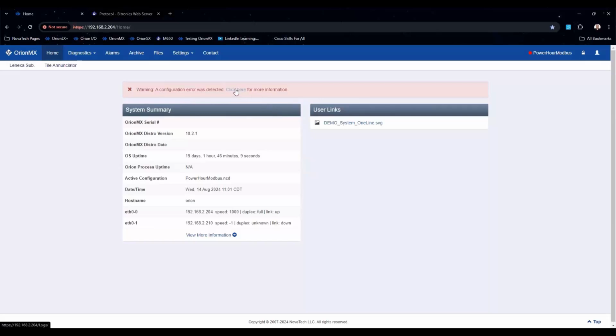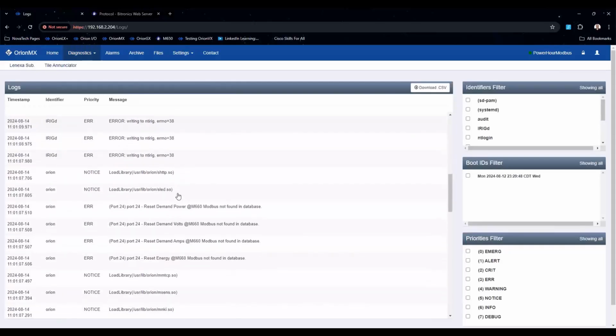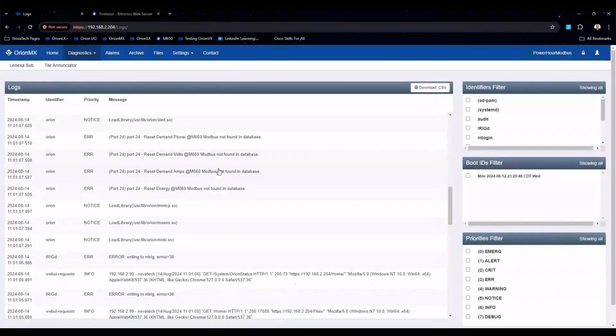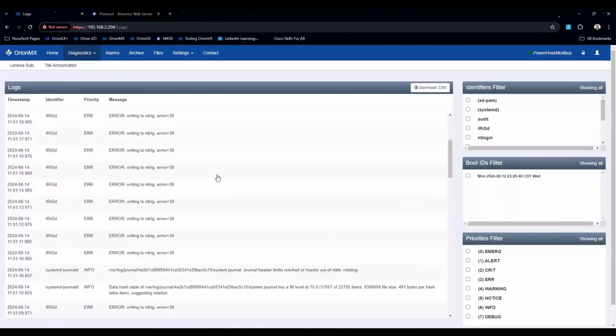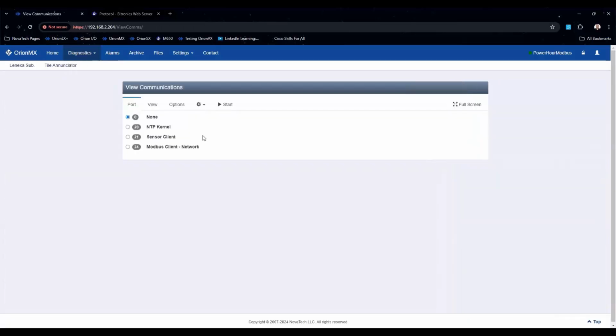This is actually something I had encountered recently in another case. Just for the sake of showing you, I will try to show you what that error said. You usually get errors here about your port that's configured, because it sees a Modbus instance configured, but since it doesn't see points configured, you have an issue with Modbus, which then forces an error on the Orion.